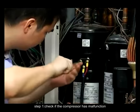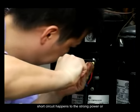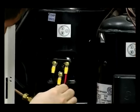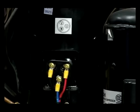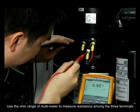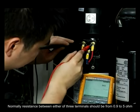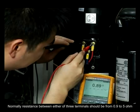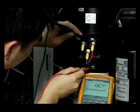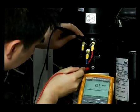Step 1. Check if the compressor has a malfunction, a short circuit happens to the strong power, or the terminals of strong power are not tight. Use the ohm range of the multimeter to measure the resistance among the 3 terminals. Normally, the resistance between any two of the 3 terminals should be 0.9 to 5 ohm, and the resistance between terminals and ground should be infinite. If the resistance is abnormal, please change the compressor.